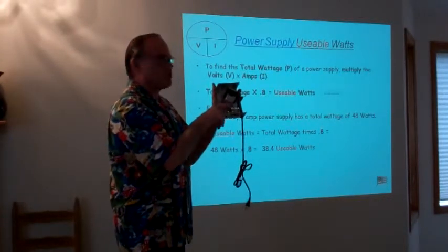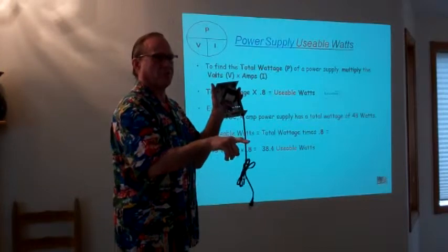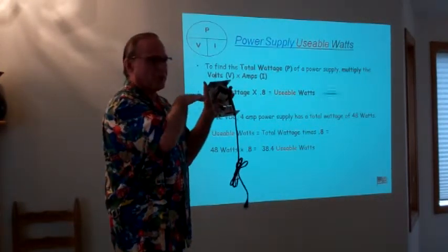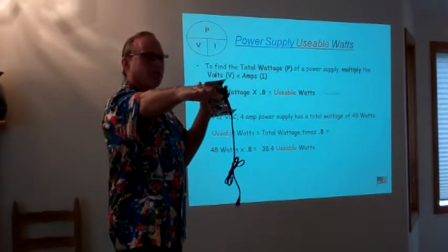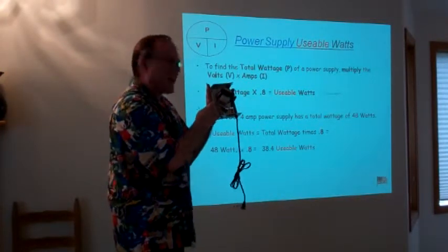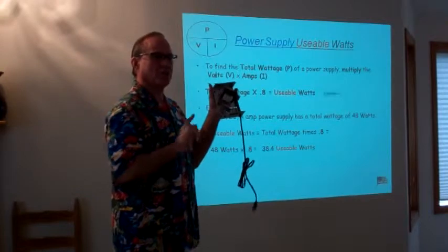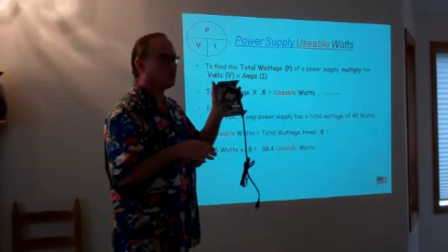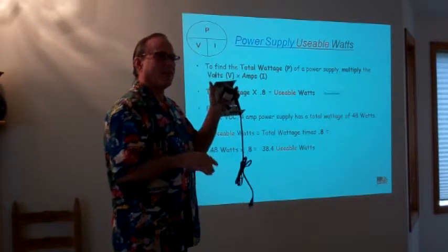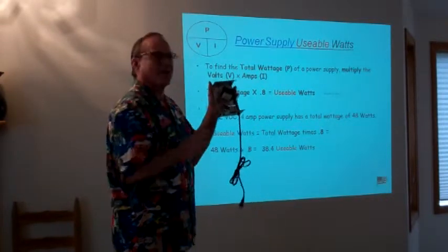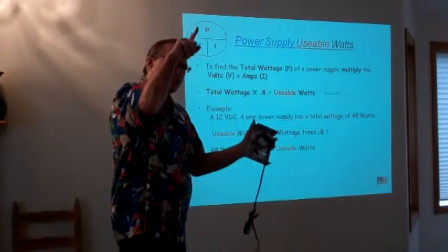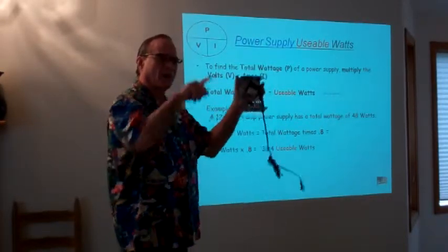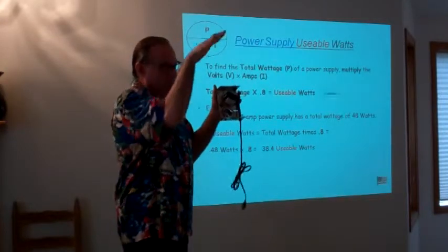What that virtually would do would create pulses for us. And remember, DC, direct current, does not pulse. It needs to continue in a steady state. So what these diodes do is they limit the direction that the current can flow. And because we've got them flipped in there at 180 degrees apart, when one side virtually is on, the other side is off. So our cycle, if you will, one's on, one's off, one's on, one's off. Because we have 2 sides to each cycle.